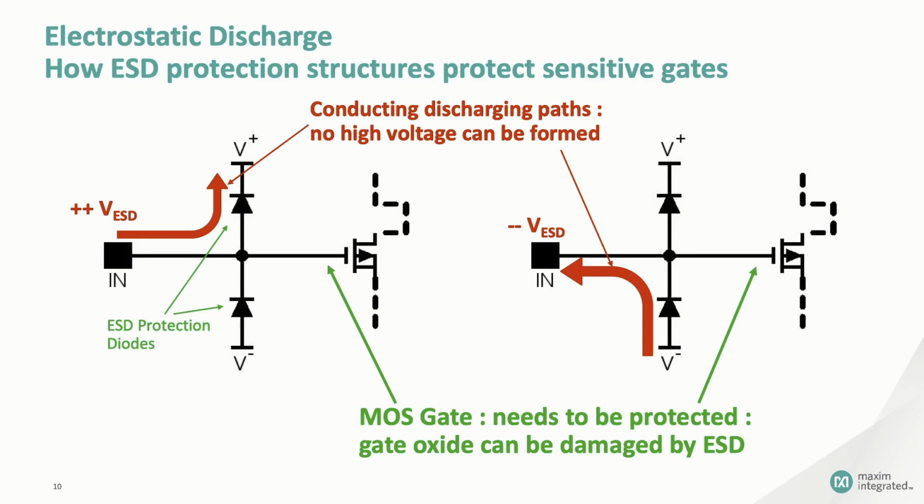Finally, we have to recognize that many electronic components go into applications that are power constrained. Now, I'm thinking about battery-operated components, especially those that have to operate for months or years on battery power. Minimizing current draw is crucial, and that means the reverse bias leakage of these diodes had better be as close to zero as can be achieved.